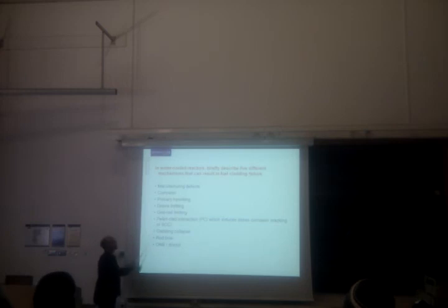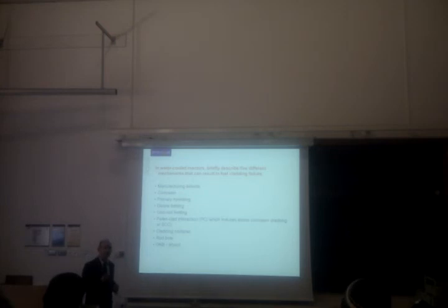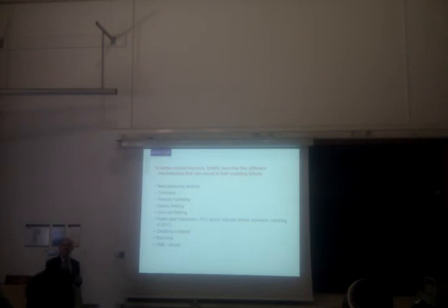Sometimes during reactor refueling operations, people leave bits in the reactor. People have left all kinds of strange things in reactors, including hammers, pliers, all kinds of things. It doesn't happen often these days, but what does happen is that people are doing electrical repair work, for example, over the refueling pond, and little bits of wire fall down into the reactor core. The grids, unfortunately, act as very, very effective sieves. And these little bits of wire get caught up in the grids, they vibrate in the flow, and they can fret or wear away at the cladding. So there are two different types of fretting that can take place.